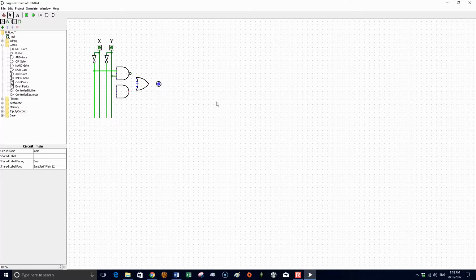The problem is that the pins on a chip, including the pin for every gate, actually have 3 states, not 2. Here we only have 2, 0 and 1, but on our actual chips there's 0, 1, and nothing connected, or a null. When there's a null, you get unpredictable results. That means for each gate you're using on a chip, every input must be connected to something.